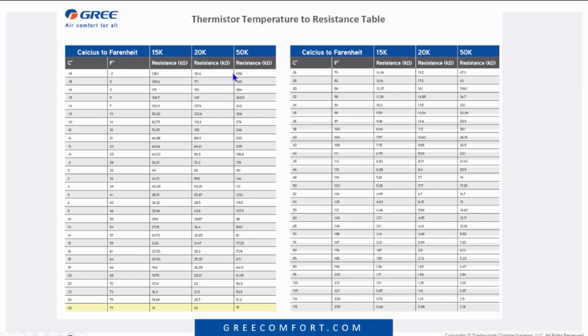And if you really want to get down to the nitty gritty, guys, and you've got a machine down, I don't care if it's a mini split, MultiPRO, it doesn't matter. You've got a bad 50K discharge thermistor. You get a hold of the distributor. They get a hold of us. We don't have the part. Order a 50K thermistor for a mini split. It's the same thing. It'll mount to that discharge line exactly the same way. The only difference is you're going to have to cut the wires and splice it in. Right. But it will absolutely work.